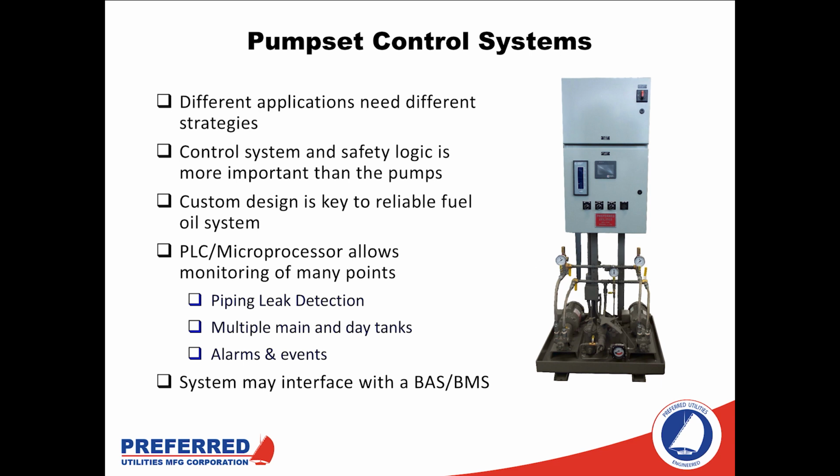Now, the advantages of modern controls where you have a PLC or a microprocessor is going to be the amount of I/O that you can look at, the amount of functionality, but also the recording of alarms and events. Much of the troubleshooting that we do on a system like this isn't done while the problem occurs. Many times it's done after the fact. And so having a detailed list that's time-stamped with a text indication of exactly what happened and when it happened is going to be crucial to making sure that this system is running in tip-top shape.